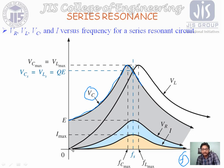Similarly for the inductor, if we start increasing the frequency, the voltage across the inductor starts increasing, goes to a maximum after a certain time, and then reduces. At the cross point of these two voltages, we obtain fs, the resonance frequency.